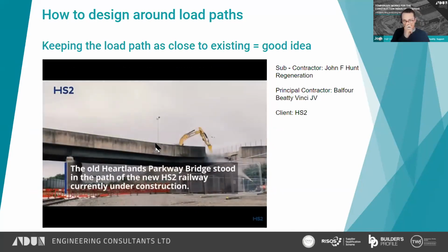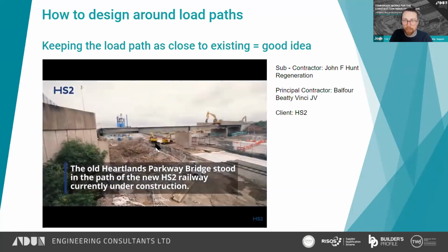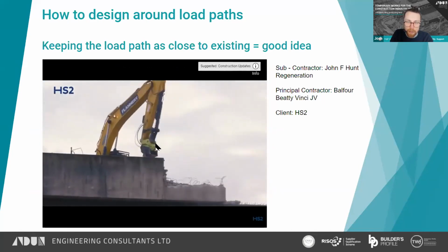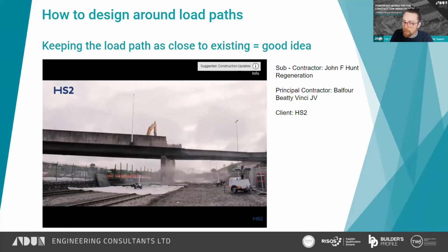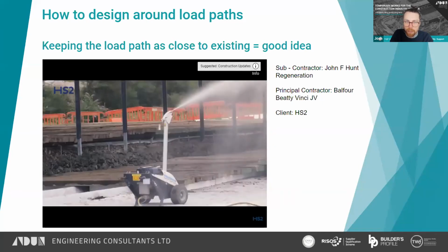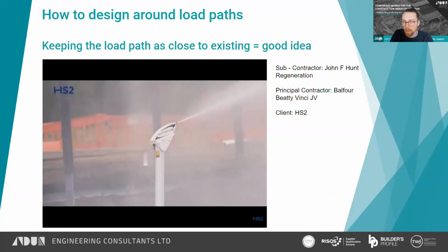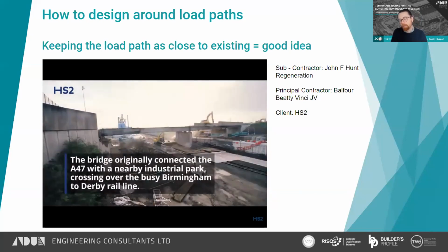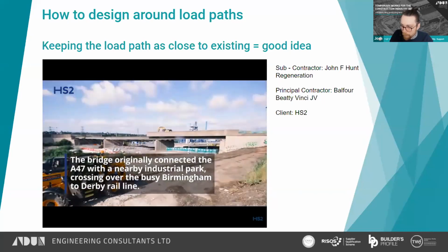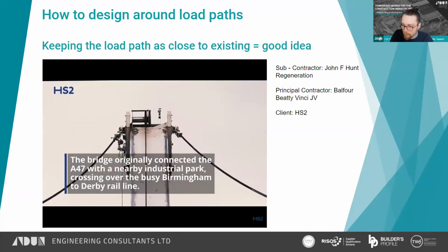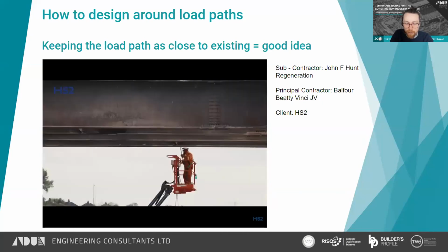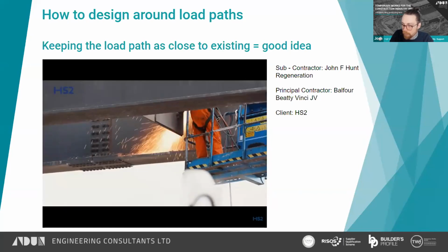As we watch this, think about how the loadings onto the bridge deck are changing as its dead weight is removed. And then what happens to the load paths once certain structural elements are demolished. Load paths can be horizontal, such as when you see that they remove the steel beams in the middle of the deck. Think about how this changed the loading going to the abutments from any lateral support.